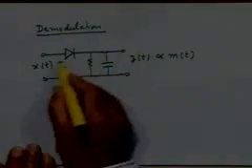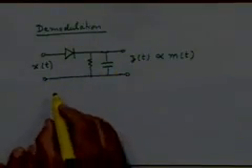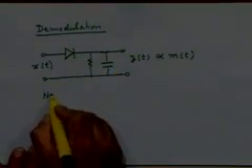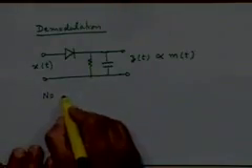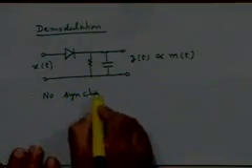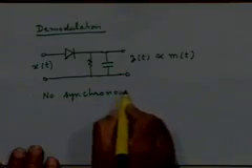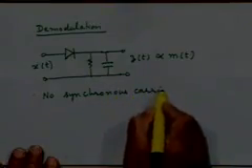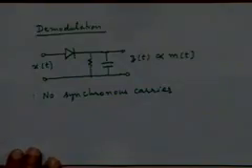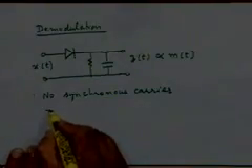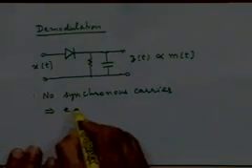So the important point is, you need to understand this operation. The important thing is that if this works, then you don't require any synchronous carrier at the receiver, right? And therefore, as a result, you don't require any expensive carrier recovery circuit.